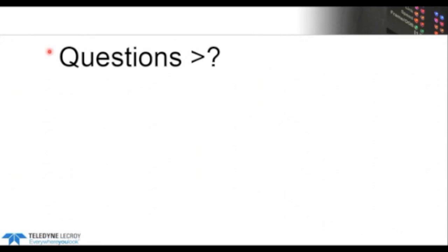Okay, well, here's one question. Someone is asking if it's possible to configure these data buffer chips in parallel, or do they have to be configured individually? That is a good question. I believe that the answer is that because of the sensitivity to each system, you're going to have to configure each buffer chip individually in a serial fashion every time you boot up.